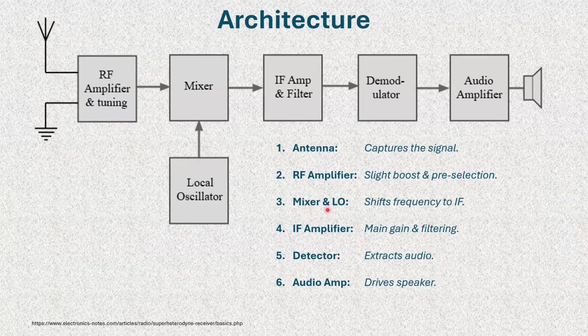Here's the mixer and the local oscillator. It shifts the frequency to IF, right? Shifts the frequency of what? Shifts the frequency of that carrier. What carrier? The modulated carrier, which means the carrier with all the information that's modulated onto it. It shifts to the IF amp.